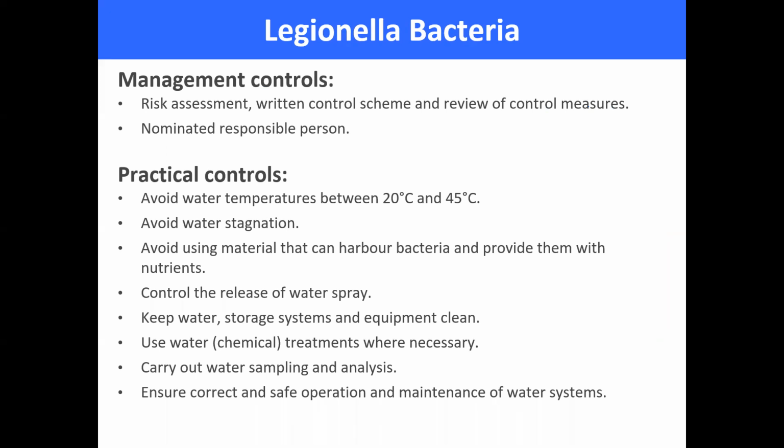What are the practical controls that we can use? Avoid water temperatures between 20 to 25 degrees, because this is the temperature where the Legionella bacteria thrives and reproduces. It needs a suitable temperature, and you need to make sure that temperature is not provided to it.